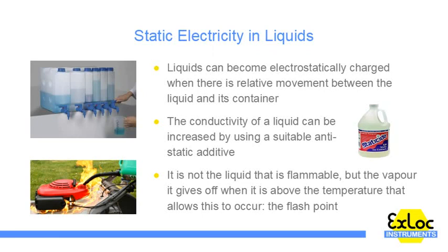In an area where multiple products are being processed, or where a container is being used for a different product to previously, known as switch loading, a flammable atmosphere may be present even if the particular product being handled at the time has a very high flash point.